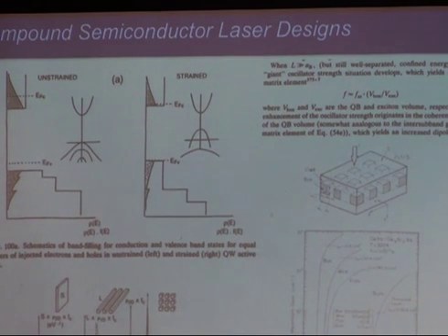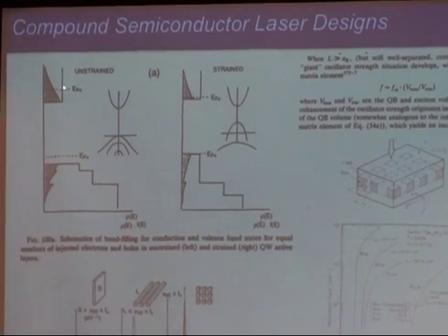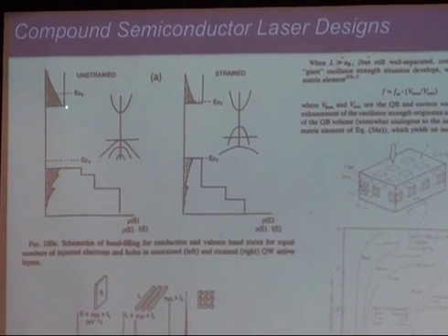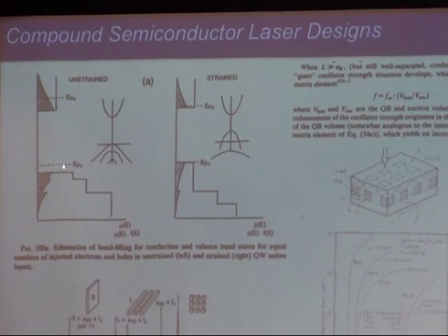I think you can see, even looking at this, that because the conduction band DOS is small, the Fermi level of the conduction band is going to climb up very high. Whereas the valence band will not climb very high because the DOS is so large. It will be stuck over here. Does that make sense? Because the DOS is high. But the EF, these FC and FV have to adjust to populate the two bands with the number of carriers you've injected. They'll be wherever they need to be to ensure that you have the right carriers there.